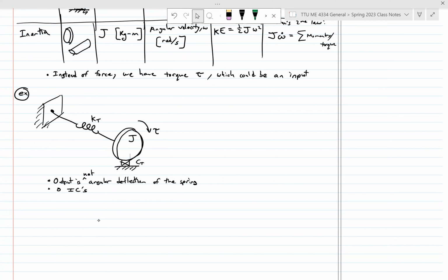Just to make sure the damper is there at the bottom. Think of it as like it's a wheel and brakes are applying onto it. The location of the damper doesn't matter. It's applying onto the inertia. I could have drawn it over here, or on top, wherever. It's going to be on the wheel. That's how I'm drawing it in this case. We could have it somewhere else, but usually I try and just put them directly on our inertias themselves.